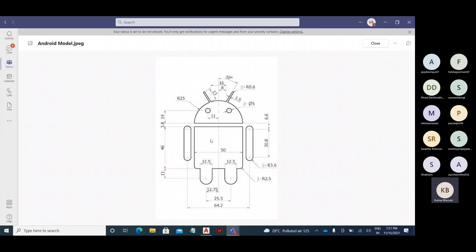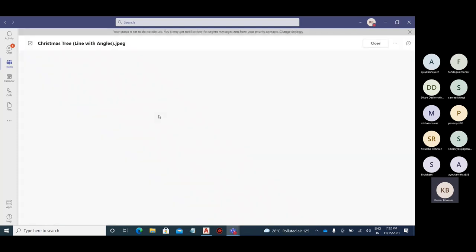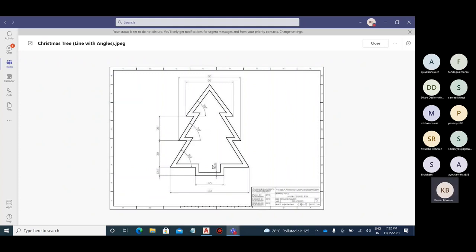You have to apply the same concepts, and these are some easy ones. Having 50 distance of lines, having fillet options with radius 2.5, these things are easy. This one is also easy. You can create the whole thing, then make it a join object, then give an offset of 4.75.